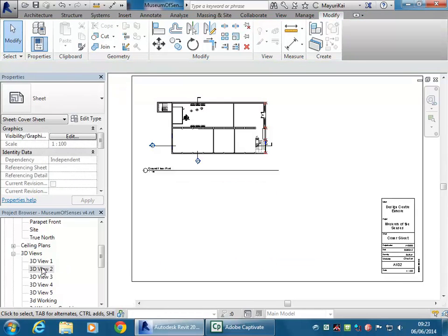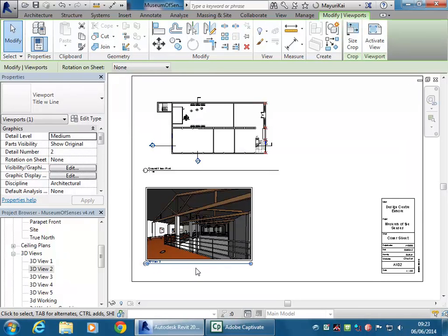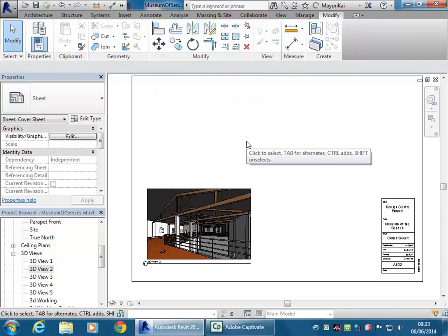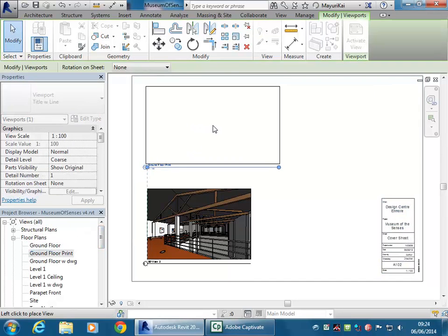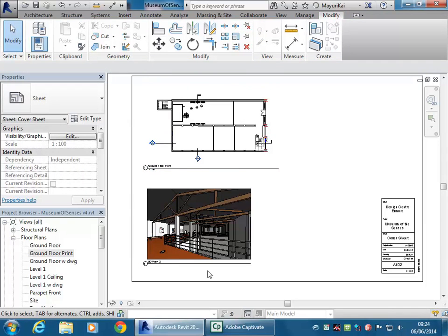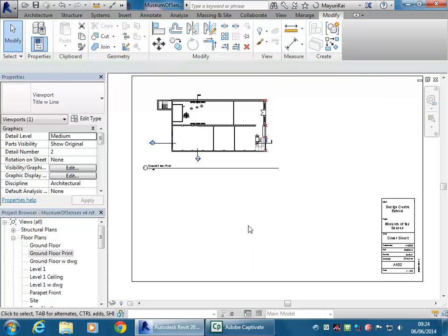If you delete the view, drag it onto the sheet again, that'll reset the tag to the new size of the view. So don't be afraid to take your views off the sheets. They're not the objects. So it's no problem if a view's causing a problem just to delete it and then drag it back on, which will actually reset a few things and make them better usually. Sorry, what was the shortcut to change the size of the title? Sure. So you just select the, to change the size of the tag, you mean? Yes. Yeah, so what I did is just delete that view and then drag it on again.